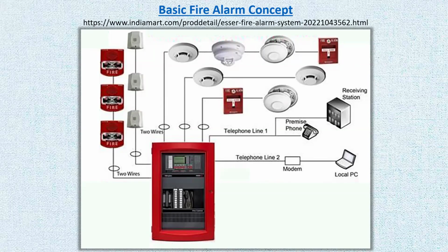Now, the smoke detectors can sub-classify into different ones. For example, there could be just a regular smoke detector that you mount in the ceiling, and it could be self-powered, but for the most part is going to be powered by the electrical grid, or powered by the fire alarm panel. There are smoke detectors that are mounted in the air ducts.